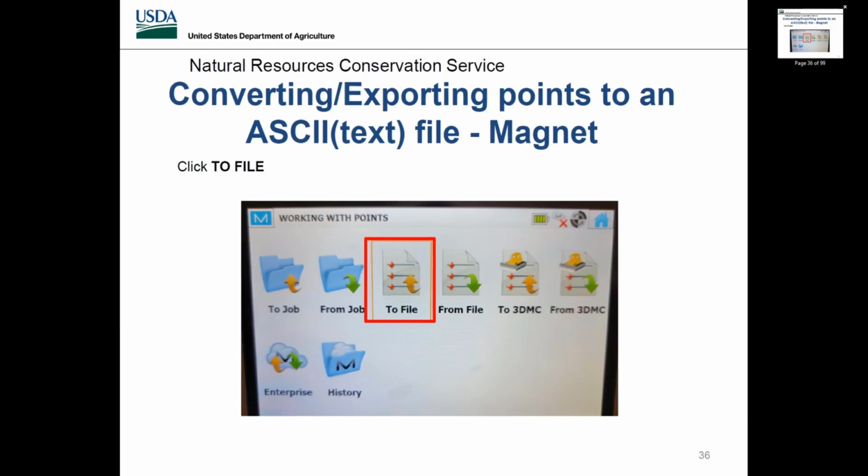And the one cool thing with even Magnet, it's got that little bulldozer on the right hand side here. I actually did a job with a contractor where I exported that file type to them, and they put it into their system because they were demoing a piece of equipment, and it had my entire drawing on there. Basically they pushed a button and the blade went up and down based off of the elevation of what my design was. That was pretty cool to see.